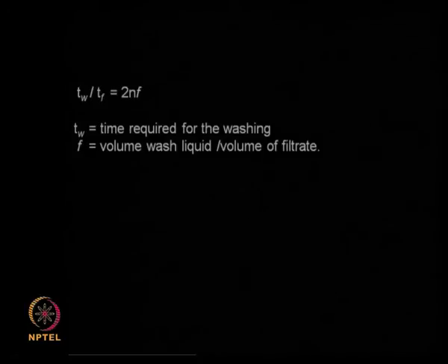the impurity present, the solubility of the impurity in the washing liquid, the efficiency of your rotating drum filter, the amount of liquid retained by the solid cake, and so on. So these are all related to the physico chemical properties of the impurity, the physical properties of your cake as against the physical properties of the washing up liquid you are using.